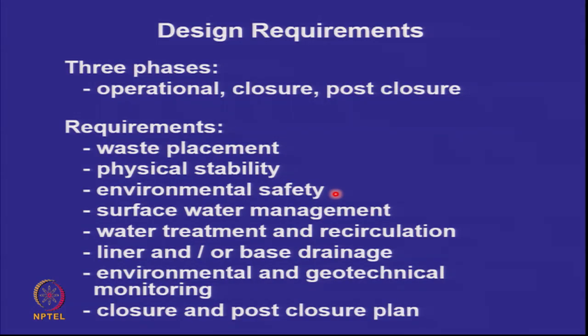Typically, on a landfill, the waste is coming in a truck and you're using dozers to spread the waste. In a slurry, how do you do it? The physical stability of the entire pond is an issue. That means the embankment stability, how high will it rise, and if it breaches, what will happen? What is the impact of the slurry water on the environment, on the groundwater table? What is the impact of the dry, fine particles blowing away in the wind?